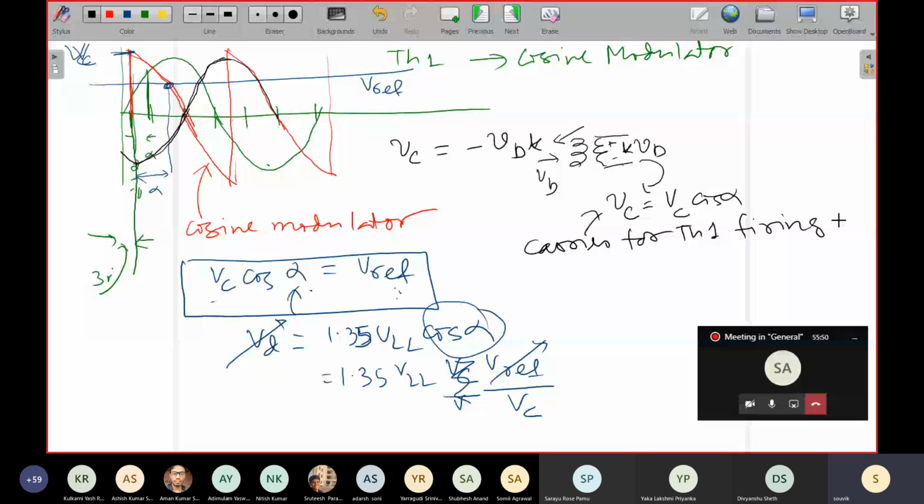However, you may argue about one minor part. This waveform has a period that is half, because we are again and again repeating it. After 180 degrees, we are rectifying, and not continuing with the VB or minus VB waveform. So how do we do it? We can do it a little cleverly by ANDing this waveform with another waveform which is positive only during this phase. Which waveform is positive only during this phase?